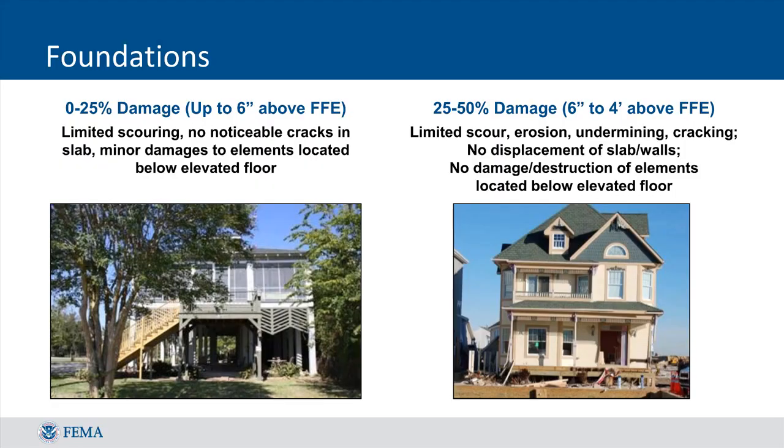If you notice some small cracks in the foundation, or if there is severe erosion or undermining of the foundation, you may increase your percent damage level to between 25% and 50%. The photo on the right shows a home whose foundation was held together with its superstructure, but which suffered serious erosion and some minor damage to the foundation itself.